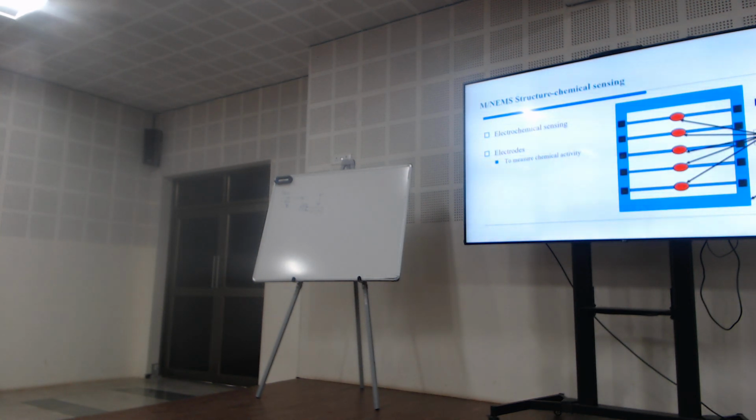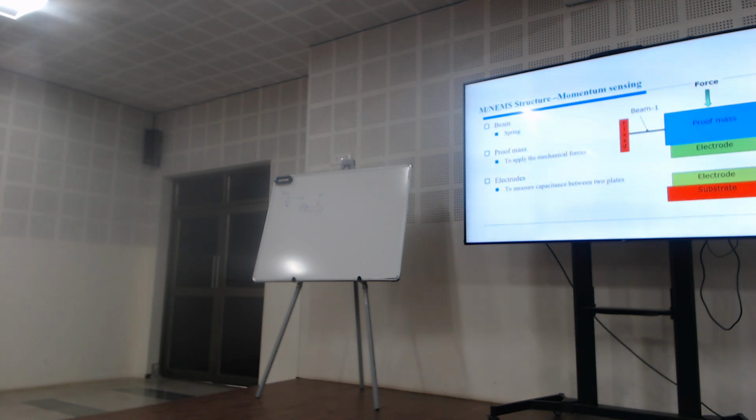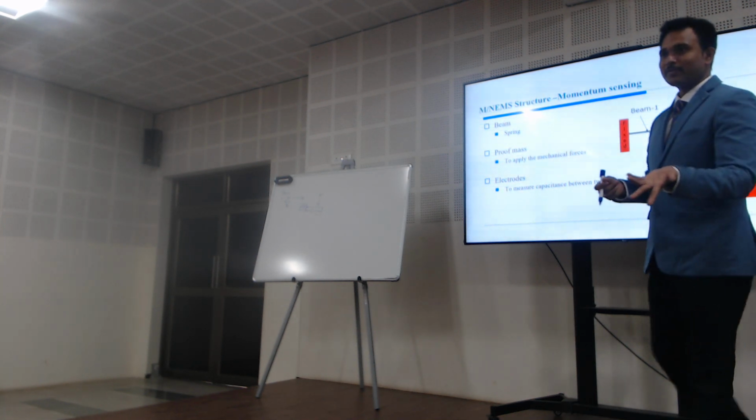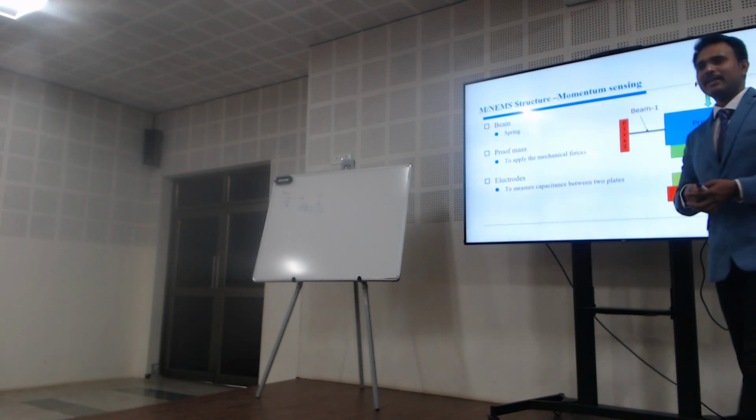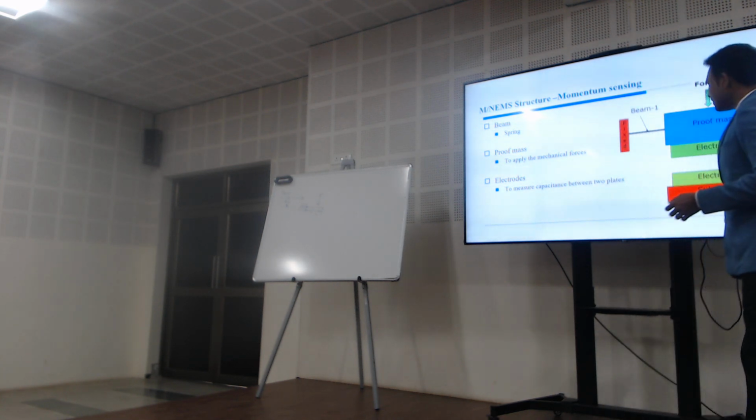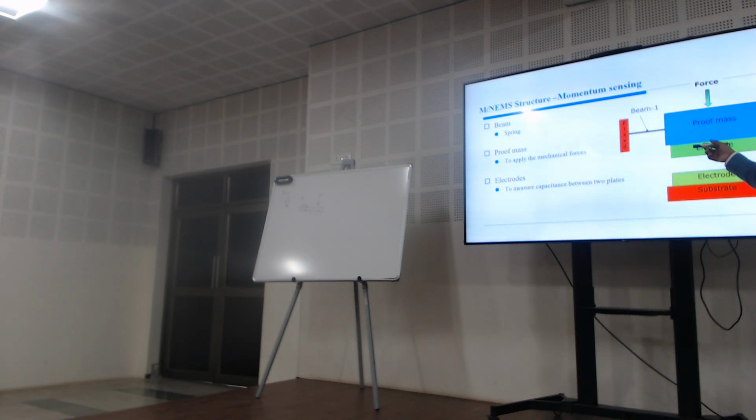And next one is the rigid sensor. Already, sir is asking one question: what about piezo? Here we are saying these are electrodes, so we simply change the capacitance. Instead of capacitance, if I keep a piezo material, force is directly converted into an electrical signal. So this electrode means a change of resistance, a change of capacitance, or piezo is also possible. That comes under the movable sensor.